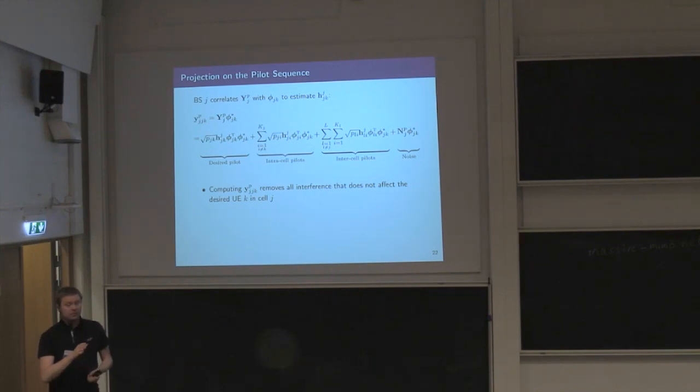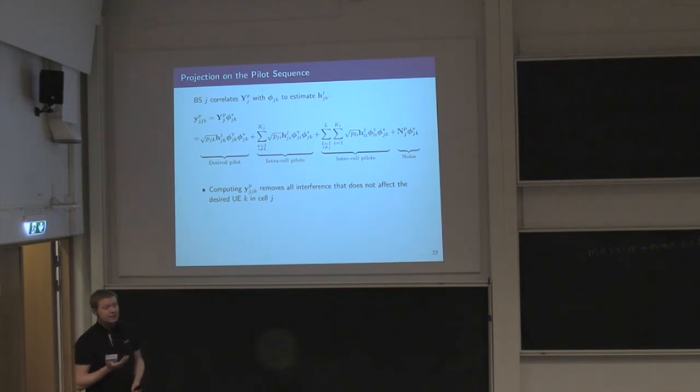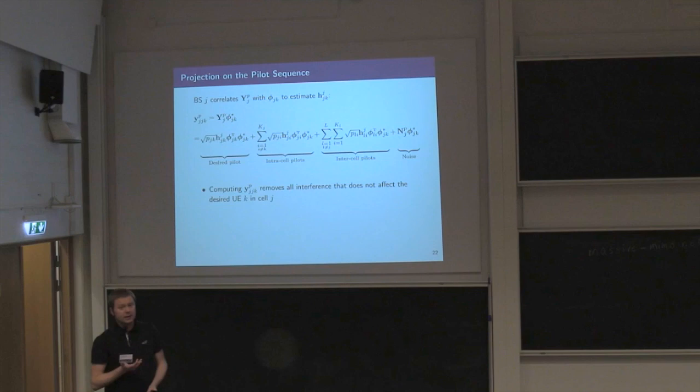So do we need downlink pilot estimation? That depends on if you have hardening or not. And as Eric was describing, you don't necessarily need to have any pilot sequences in the downlink in order to learn the channels, even under imperfect channel hardening. The important thing is that you have a lot of antennas, or that you're sending a long block of data so you can use that to learn the channel anyway.